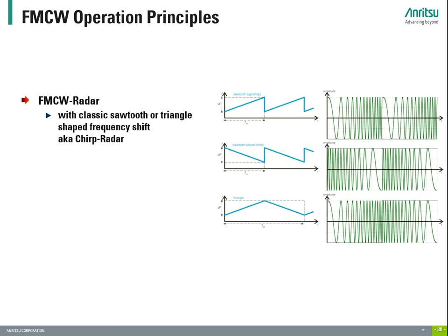The main concept behind any FMCW radar is a signal which is known as a chirp. The signal can be understood as a sinusoidal wave with a frequency value that increases linearly with time, as presented here on the slide as amplitude plot in the upper part and as frequency time plot in the lower part. The linear change characteristic of the chirp signal creates a sawtooth-like frequency behavior.